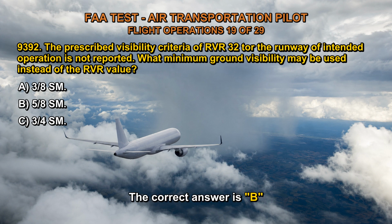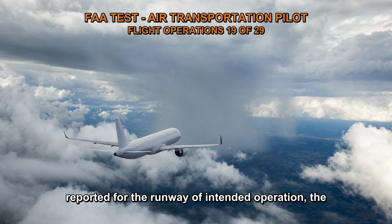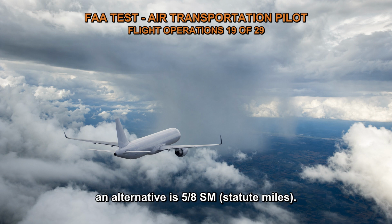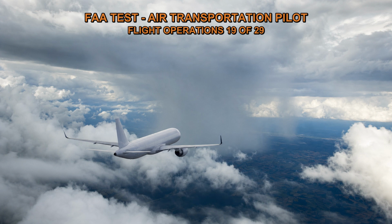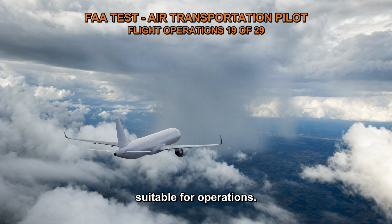The correct answer is B. When the runway visual range, RVR, is not reported for the runway of intended operation, the minimum ground visibility that can be used as an alternative is 5/8 sm, statute miles. This is specified by the FAA, Federal Aviation Administration, as the minimum visibility requirement when RVR is unavailable. It serves as a substitute to assess the visibility conditions for determining if the runway is suitable for operations.